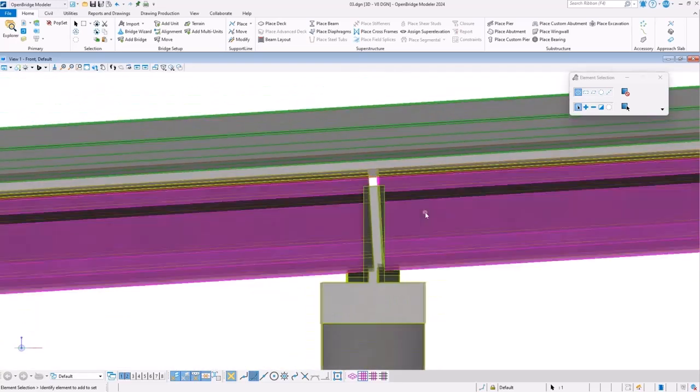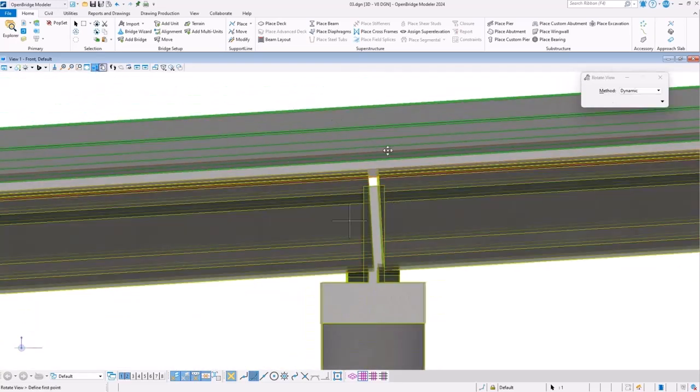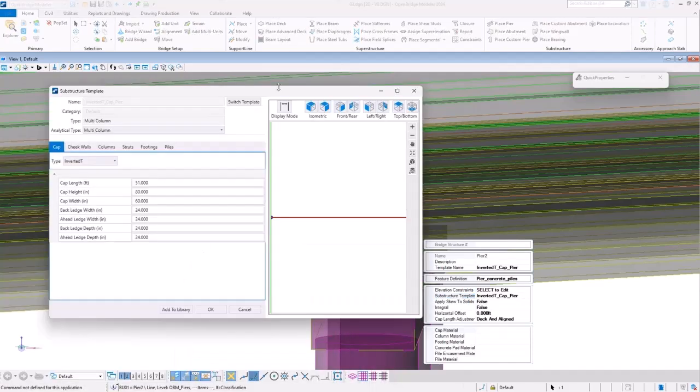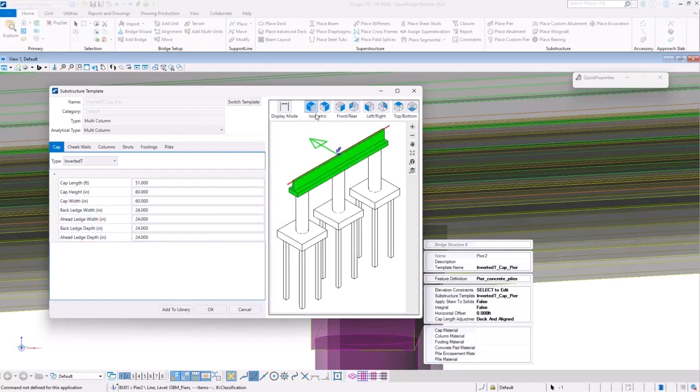And I specify different ledge dimensions for the T itself, each T or all the beams, right? So where is that done? It's actually on the substructure template. So if I go and edit a particular template, I need to activate those options of ledge and they follow the profile. Right? So I can just put different dimensions and you can see it react.